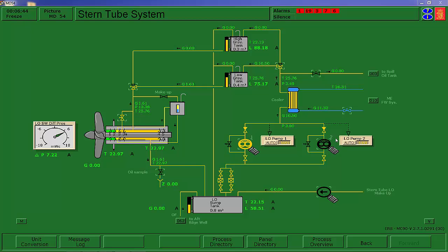You immediately have to notify the first engineer, shut the turning gear down, and investigate why there's water in a cylinder. But in the worst case scenario, as that cylinder comes up with water in it, it would stop the turning gear. It really wouldn't do any damage. Prior to getting the plant underway, you would typically have to have the lube oil up and running, and that would include not only the main engine but also the stern tube.